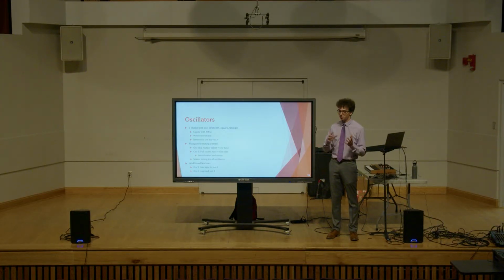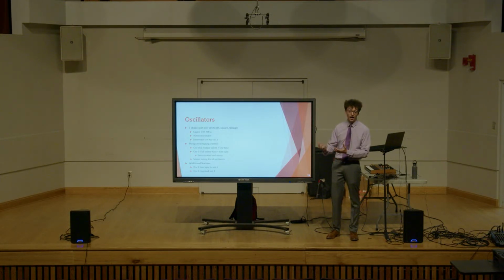And so I wanted the control scheme for these oscillators to be a Moog-style scheme where you have selections for octaves. So you'll have one octave, an octave higher, an octave higher, an octave higher, and then from there you'll have coarse tunes. So you can sort of detune and do all sorts of wacky stuff between these oscillators. And then I wanted the third oscillator to have just an entirely coarse tune knob for its entire frequency range, so it's not reliant on this selection of octaves. And that again will play into it being a modulation source, which I'll mention later.